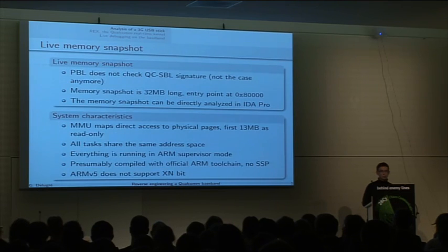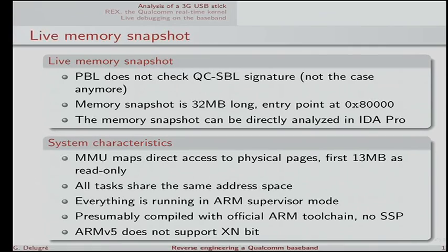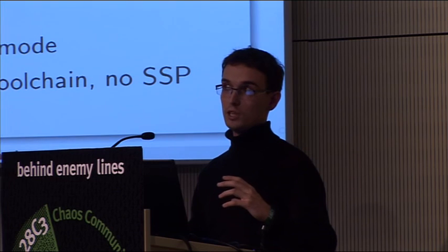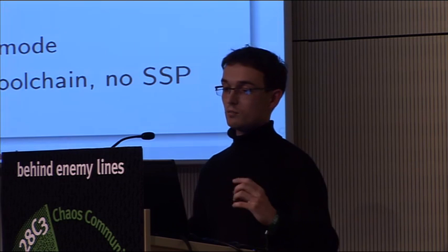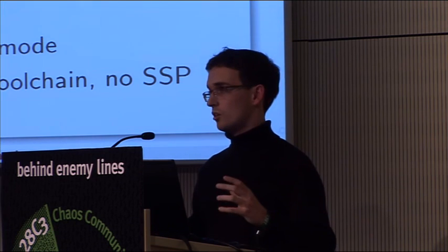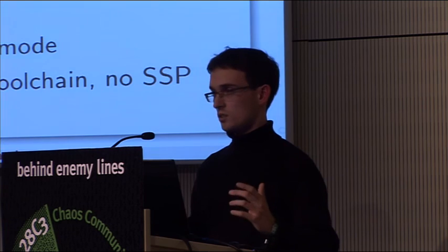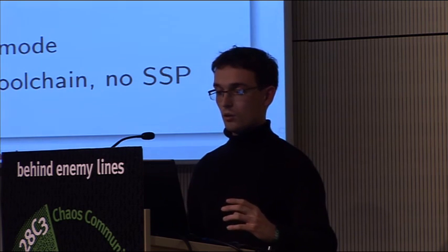So, as I said, you can dump everything in RAM, in the baseband. So you've got some kind of a live memory snapshot, which is nice. It's not actually a real memory snapshot, because each time you call to read a single byte, the task which is handling your request will have been scheduled by the operating system. So the image you get might not be totally coherent, but in practice it's fairly efficient.